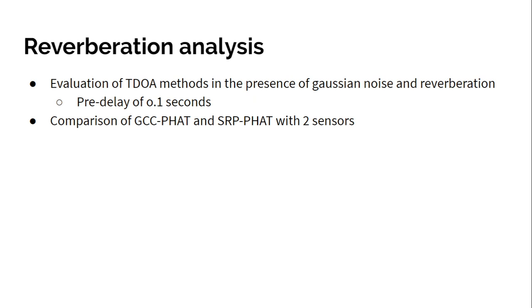Right, now we're going to conduct the reverberation analysis. I believe I said earlier that these filters were not designed for reverberating environments, but the SRP-PHAT actually has a really interesting property. It can be used in this kind of scenario because of the explanation we get in the end that addresses some reverberation issues, and we can also see it as the beamforming process.